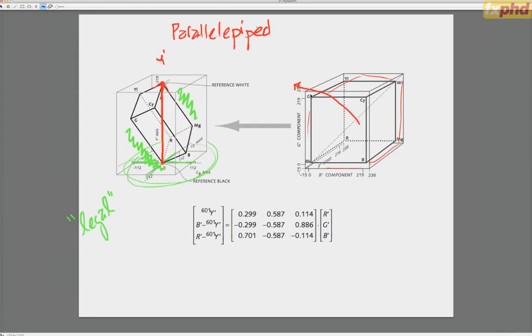So the RGB cube almost fills RGB space. Now here I've drawn the version of the cube that shows you studio video coding. So from 0 to 219 in 8-bit space is the scale from reference black to reference white. And really black is down at this corner and white is up at the other corner. So I've left the footroom and headroom regions that are standard for studio video. But even without the footroom and headroom regions, when you do this mapping to bring the RGB cube into YCBCR space, there's huge regions that are unused.